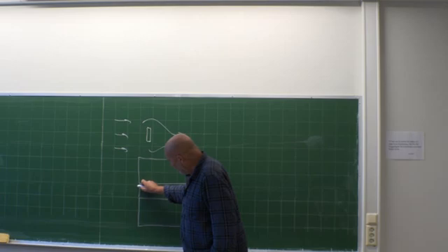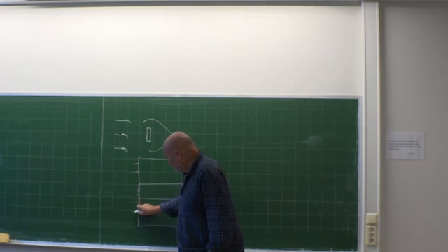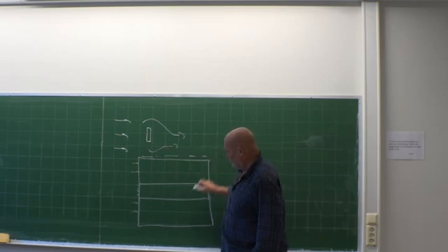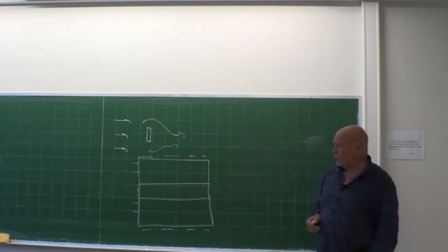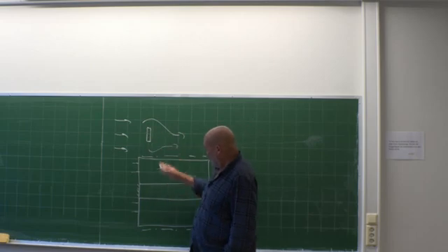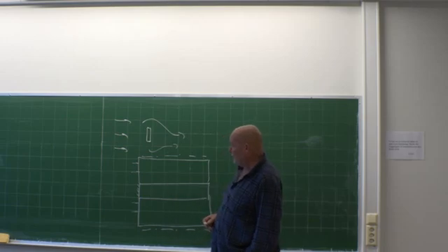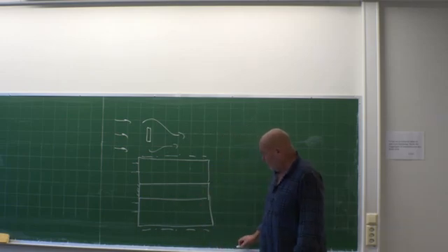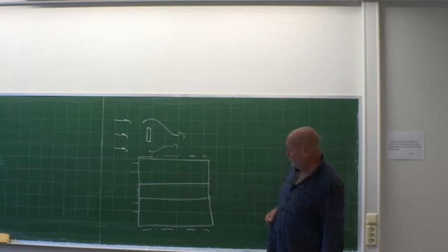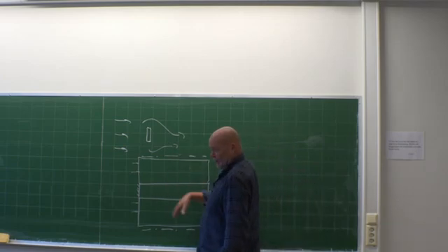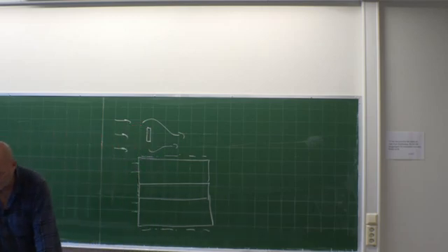Then I just specified a solid wall here, but here I have inlet velocities, and then I used symmetry on top and bottom. Of course, you could put such an object in the middle of your computational domain. That would also be an option, but I just wanted to do it as easily as possible. So this is the setup, 3 different blocks, and then I stretched the mesh a little bit, so I had a nice resolution for the center region.